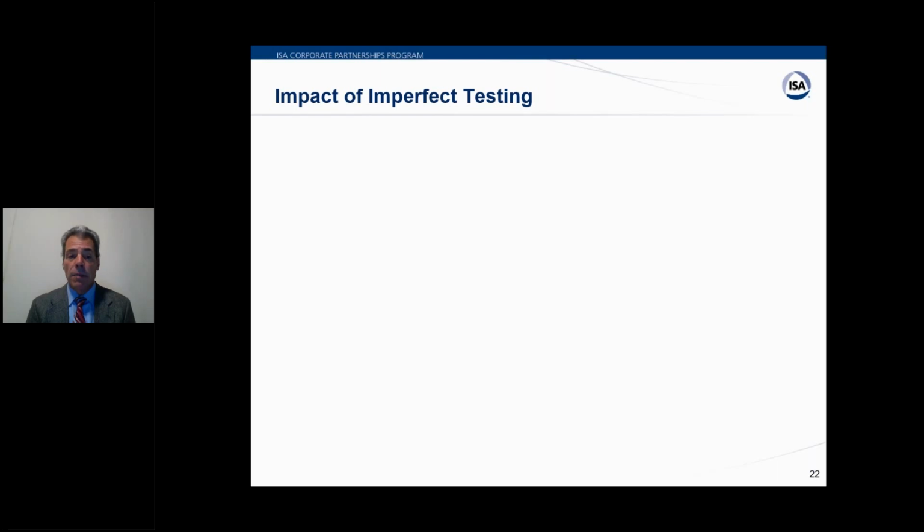The model that I basically did a moment ago with the numbers assumed for that transmitter would be assuming pretty much a certified for use in SIL 2 transmitter with a 90% diagnostic coverage. Most general transmitters only have in the range of like 30 to 50% diagnostics, and that would not meet the SIL 2 kind of performance requirements. Okay, thanks. If you're going to claim 1 out of 2 sensors, it would need to be 2 sensors specifically